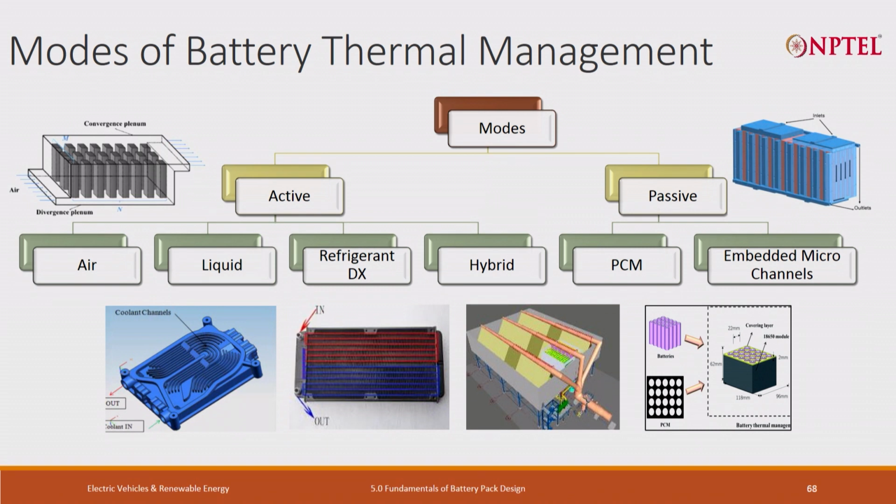So with that, we have discussed various modes of thermal management system, both for large packs and small packs, and based upon the requirement we select either active or passive, and once we select, then we start designing. First we try to get the heat load condition, and based upon the heat load condition we calculate all other things together, and then we design.